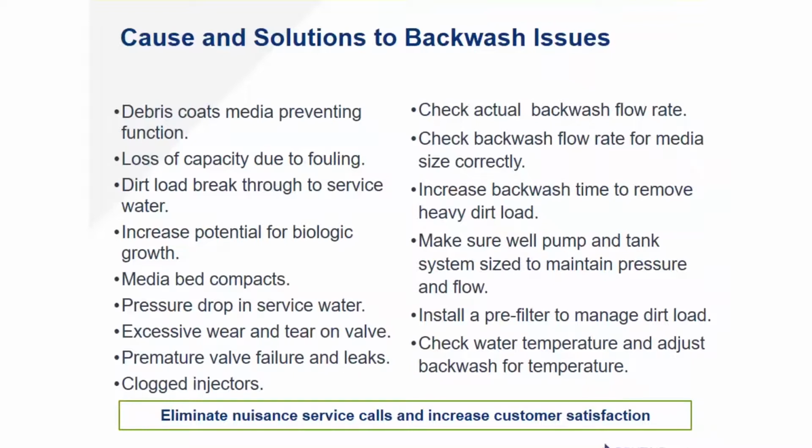So it's one of those things, if you're dealing with a lot of iron or sand or colloidal particulates, install a pre-filter, protect that equipment and reserve it for the purpose it's supposed to be doing, which is ion exchange. Check water temperature and adjust backwash for temperature, especially if you're below the Mason-Dixon line. I kind of draw a line at the top of Tennessee where I start looking at backwash temperatures based on groundwater and seasonal temperature loads.